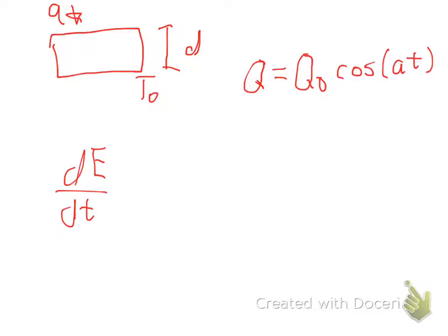Can we just pause for a second? Because you haven't finished telling us all of your assumptions. So we have a bottom assumption at some depth where we have a steady temperature T0. We have a top assumption that's your seasonal or cyclical heat flux in. Are you assuming one dimension and that it's infinite in the two other directions? Yes. We're also assuming constant density, constant specific heat, and constant conductivity, and that they're isotropic. Okay, great, so it's a slab. With that, we can simplify it down to just what's happening in the x direction.